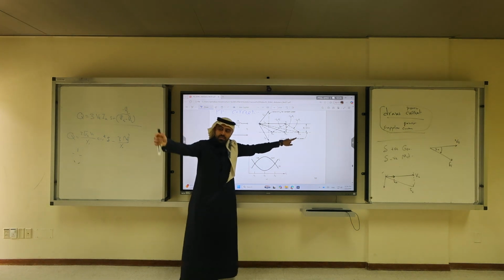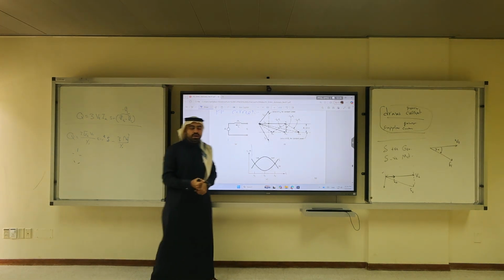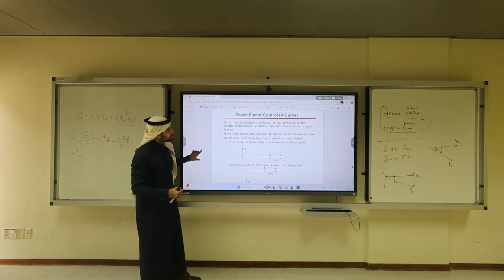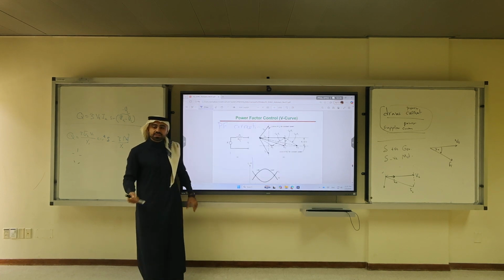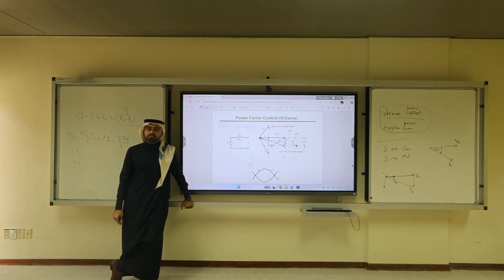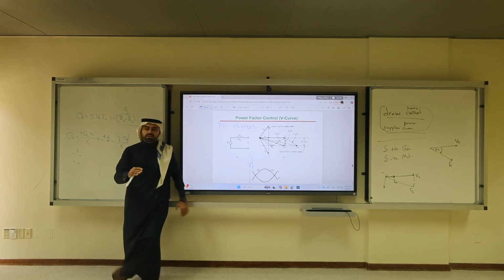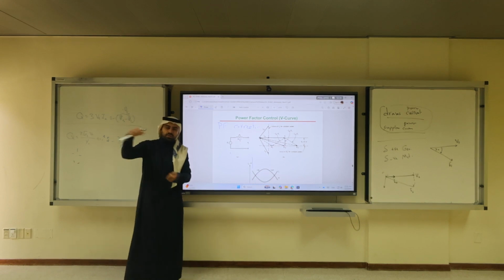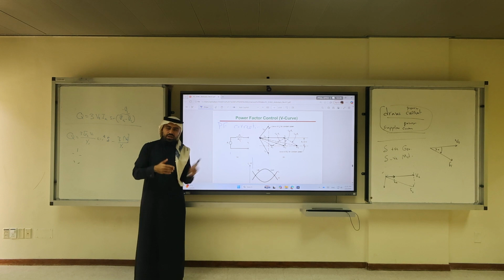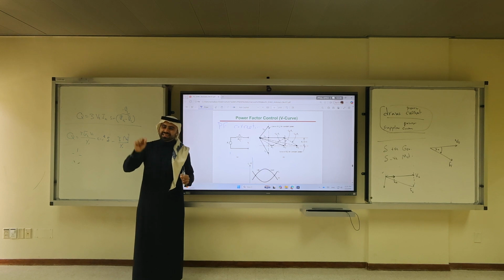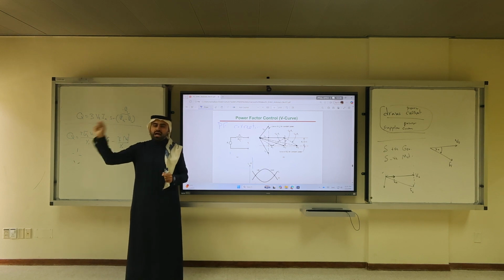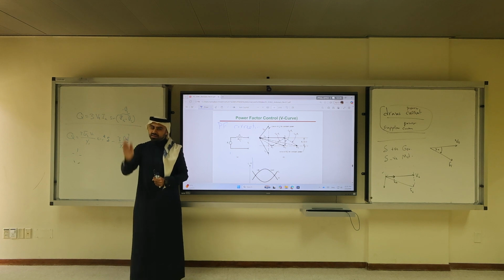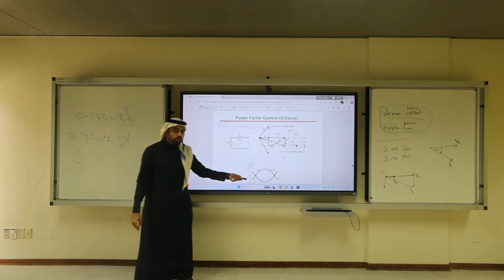I'm paying cost, I'm paying money, I'm increasing the excitation. So why do I do this? Why not just put a capacitor? Because capacitors are expensive. The motor is cheaper. It's not only that: to change a capacitor, it's a capacitor bank. You increase them incrementally, you connect multiple banks. However, with this, you can have linear operation, so you can have a power factor of 0.8654031 that accurately. The capacitor bank is incremental, because here you can control the field.